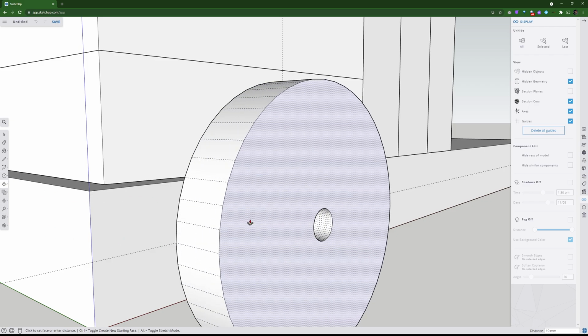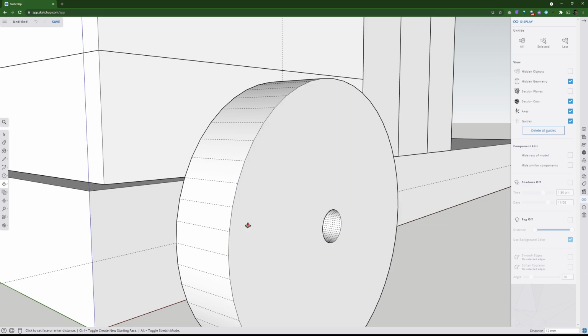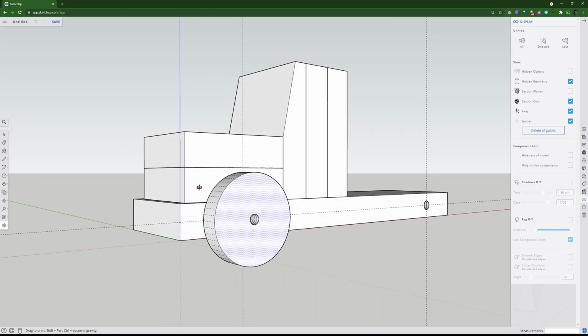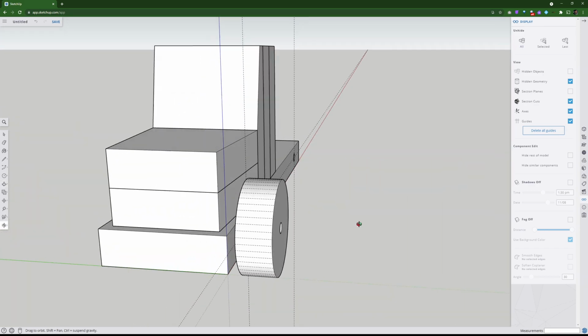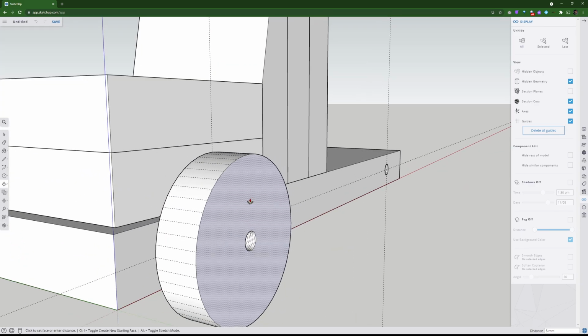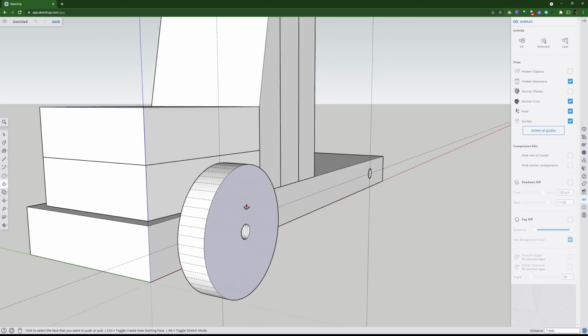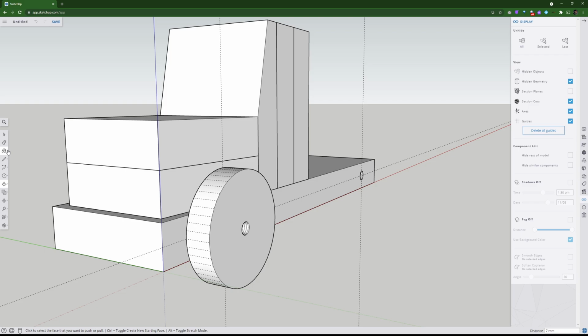And then I've got to make a decision whether I'm going to come out 12 mil and use 12 mil material for this, which looks quite good actually, or bring it out another 7 mil, 19 mil. In fact, I think I will do it 12. So I'm going to come back in here, 7 mil. Now, to make the wheels look a little more wheel-like, I'm going to do another hole saw in there. Maybe I'll use a 38 mil. Let's have a look what it looks like.